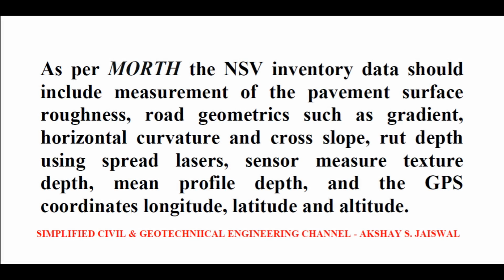As per MORTH, the NSV inventory data should include measurement of the pavement surface roughness, road geometrics such as gradient, horizontal curvature and cross slope, rut depth using spread lasers, mean profile depth and the GPS coordinates longitude, latitude and altitude.